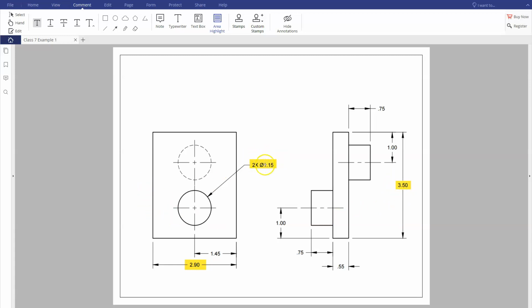This dimension or diameter represents how long each one of these lines that I have highlighted are. So you can imagine that this is a physical piece, something like a Lego block without the recessing on the inside. Let's switch over to AutoCAD, and you'll see that we'll have to jump between both of these views in order to pull some information that we need. That's going to be typical when you start creating projections: not all your dimensions will be on one view. You're going to have to start referring back to the other view in order to create it.